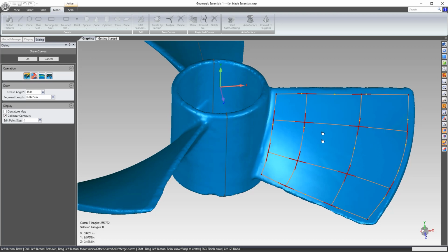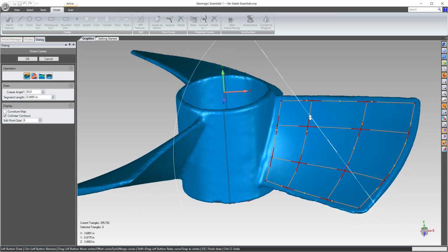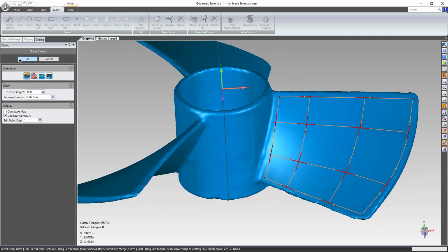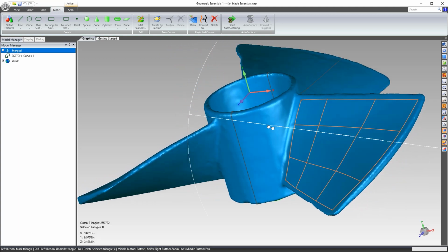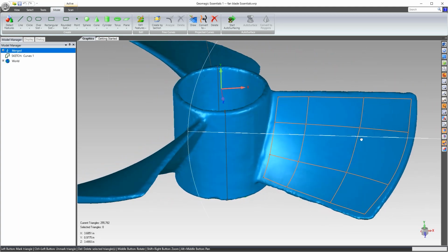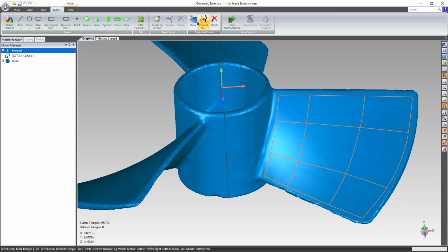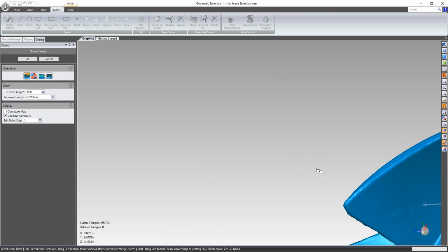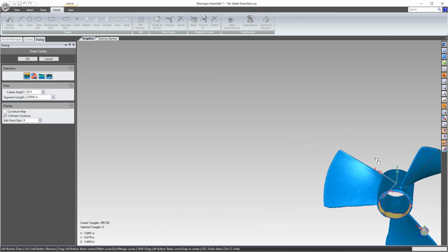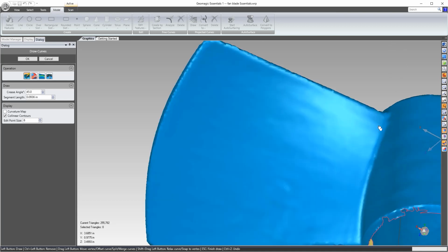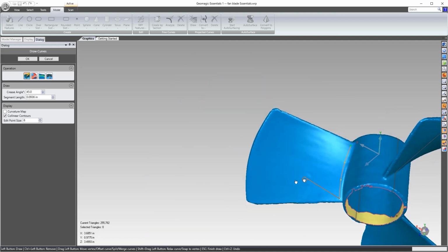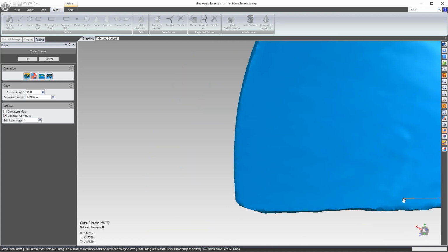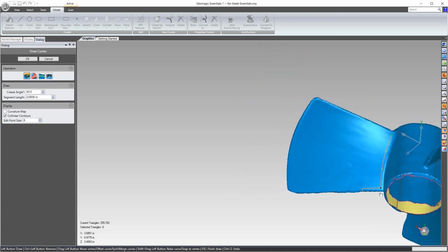So these are just to give me enough resolution to draw them inside of Solid Edge or convert them inside of Solid Edge. So you can see that I went ahead and I selected those curves and I drew them. Now, actually, let's go in and draw them on the other side because this isn't necessarily a constant thickness blade. If it was, I would just draw one side and offset the surface that I use, which, many of the companies that make these, they all know when they're designing it whether it's supposed to be an offset or a constant thickness blade.